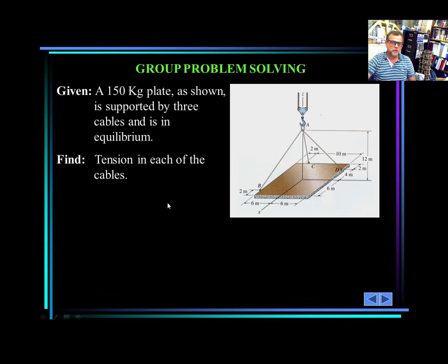How are you going to solve this problem? Same way. Do particle equilibrium. You can do this by doing rigid body equilibrium, but we haven't covered that yet. So the only particle that involves everything is right here, particle A. Of course, the weight is acting here at the centroid, so how am I going to move that weight from here to here? Well, this cable has to be supporting the whole weight. So basically, it's like putting the weight acting up and doing this equilibrium here. What is the main objective?